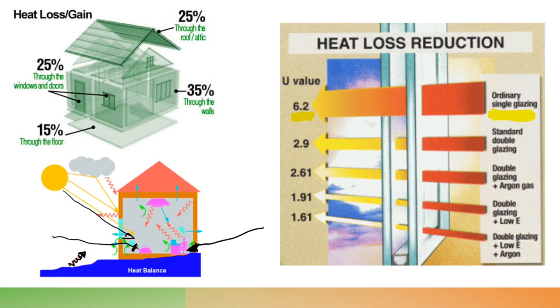What was the maximum permissible allowance for watts of energy to pass through a fabric, from inside to outside? Oh, we've got the highlighter pen on, that's why. Let's change to a pen, and it was 0.33 watts per square meter per degree difference.